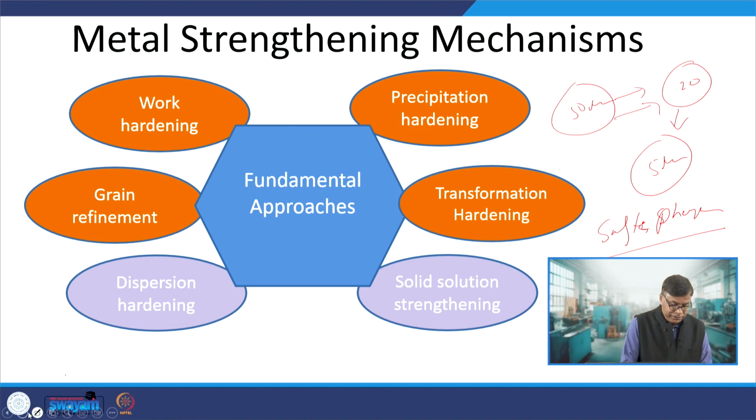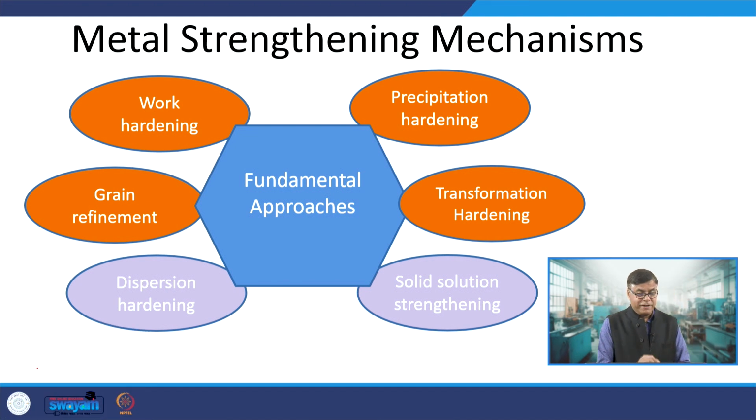So, the relative effect of the grain refinement is somewhat limited as compared to the phase or phase transformation which can happen during the deformation. So, that is what we can call transformation hardening. Initially you may have soft phases offering very good ease of deformation and plasticity, but in the course of deformation or thermal treatment or high temperature deformation, if it leads to the formation of hard phases, then this will make the job of deformation difficult, reduce the plasticity, and decrease the ease of deformation significantly.